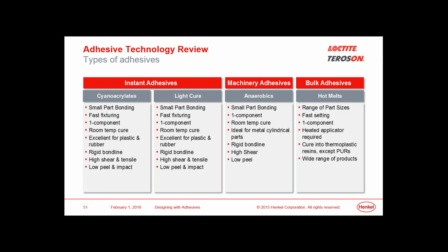But we're augmenting the seal and we're increasing the pressure resistance and we're increasing the long time performance with the anaerobics. Another major advantage of anaerobics with all of these applications is not only do they seal, but they protect from corrosion. In fact, most of our adhesives can be said to protect from corrosion in any of the applications that they're on because they are a polymer that is going to prevent water and moisture from entering the assembly and causing oxidation to occur. Many times when we disassemble parts that have been aged and have rusted, you will see that there's very little rust evidence inside where the adhesive was present.